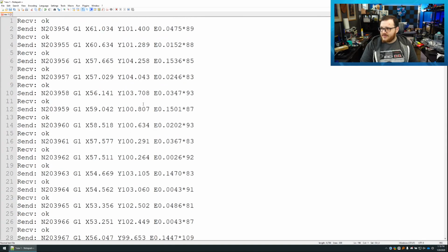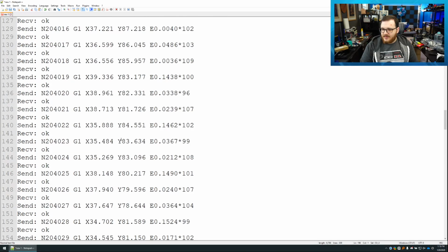So this was telling it to heat for a while, and what happens is I do run my layer fan on this ABS machine at about 40% speed, and it's a very powerful fan. Not having a good PID tune on here, because I updated the firmware and cleared the EEPROM, which wipes out the PID for that machine, in conjunction with the layer fan and not having a sock on the heater block, made it so it was having a hard time maintaining temperature.